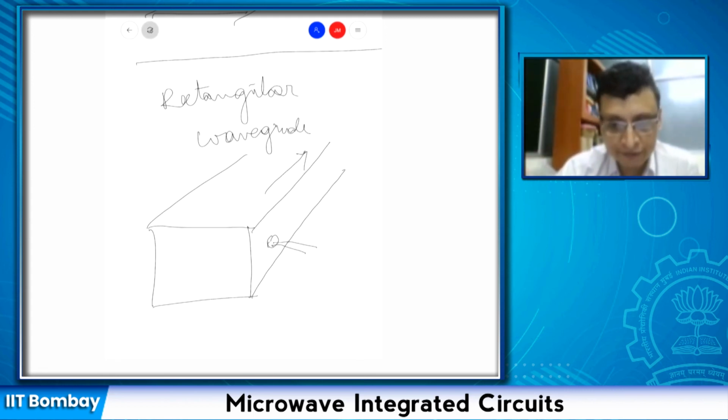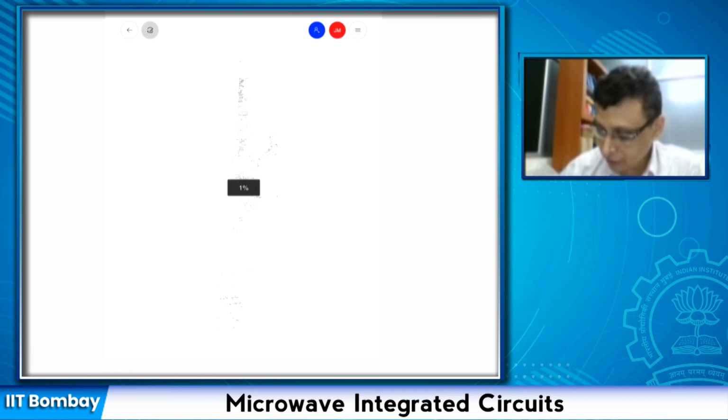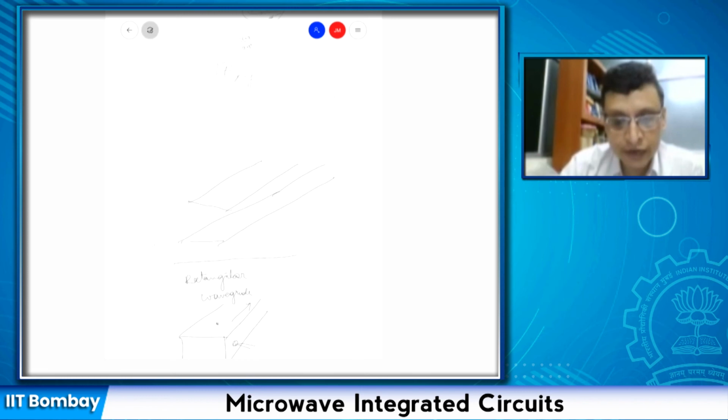In a simulator, say you are using HFSS, you can specify at the beginning, at a starting point anywhere in the waveguide, that the wave going there is the TM mode. So we will decide it. You can decide that, say at this point, the wave being introduced on this waveguide is the TM mode. So you don't need to worry about how the TM mode reached this point.